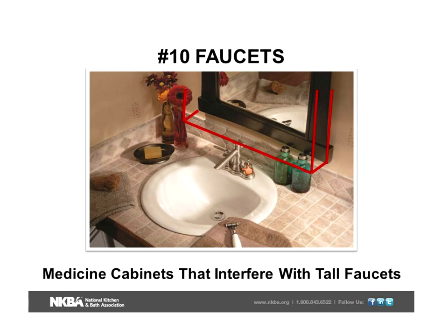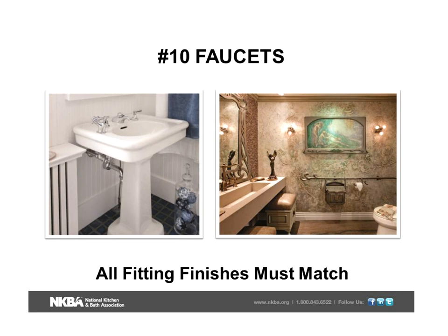By the way, with your faucet, higher faucets, watch these mirrors that are not recessed into the wall. They're going to create a real problem for you. And finally, with a finish, make sure that all the fittings match the other parts of the plumbing. Here we see the P-trap, the tailpiece, all of that needs to match when you're working with pedestal labs and some of the open base vanities that we have, or labs that we have.